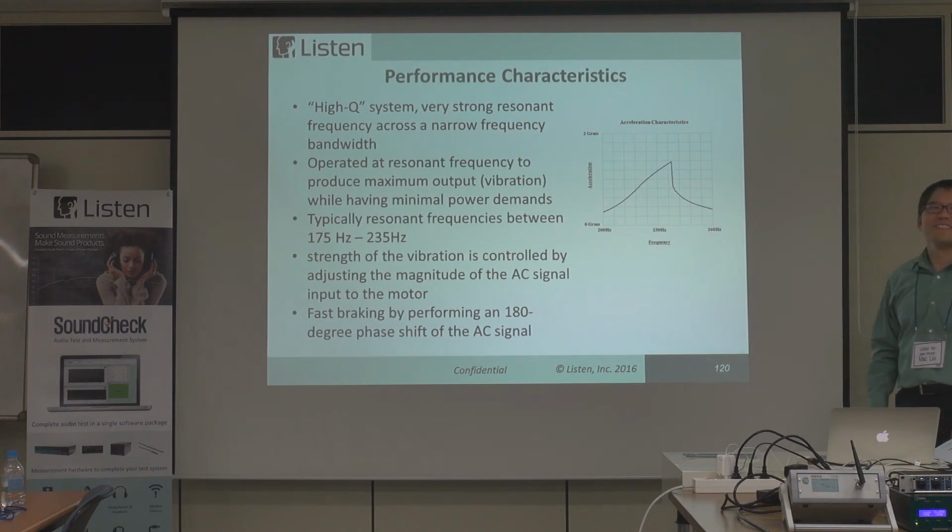So this is actually measuring the acceleration. The impedance will look more symmetric when he does the demo, because there are two things being measured. There's the electrical impedance of the resonator, and I think you'll see that's more typical loudspeaker Q. And then there's this acceleration, which is really what we would call attack and release, like we do with hearing aids.